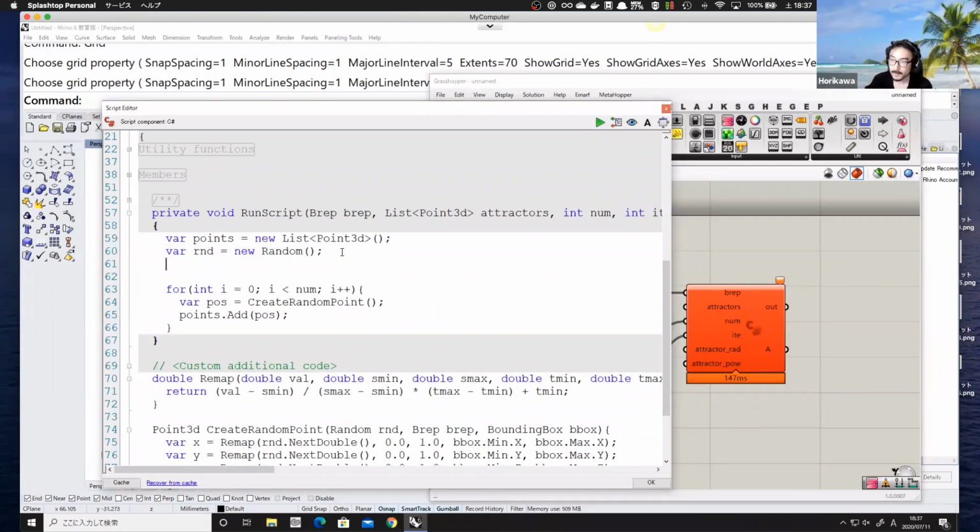And for the bounding box, we're going to create it from this B-rep. So that will be easy. We're going to name this bounding box BB box, and we can get that bounding box from the B-rep by accessing brep.get bounding box. For a parameter, it asks you to set the Boolean accurate. So if you want to create an accurate bounding box or not, we'll say yes, because we're just going to create one bounding box for one BREP. So that's not that expensive if it's one calculation, right?